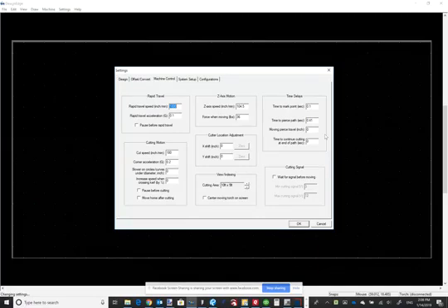And it's worth noting here that the advanced machine control also adds the cutting signal box, the wait for signal before moving. Without that, the machine doesn't pay any attention to the voltage sensing wires in the harness going to the torch. It doesn't care when the torch fires. It doesn't care when it's not firing. So it can't give you any error that it lost the torch signal while it was cutting. If your plasma cutter gets turned off or the air compressor is not on, it'll just keep running through the path, and you'll have no idea where you stopped. With this checked, it will stop and tell you, and it'll also wait.